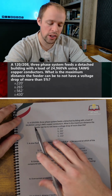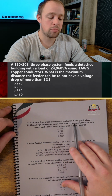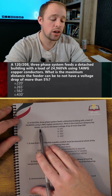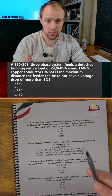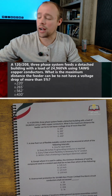A 120/208 volt three-phase system feeds a detached building with a load of 24,960 volt amps using 1-gauge copper conductors. What is the maximum distance the feeder can be to not have a voltage drop of more than 5%? This is probably a journeyman's, if not a master's licensing exam question. We're not going to be using our code books.